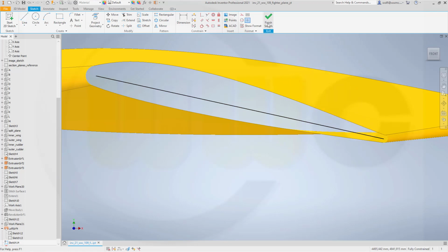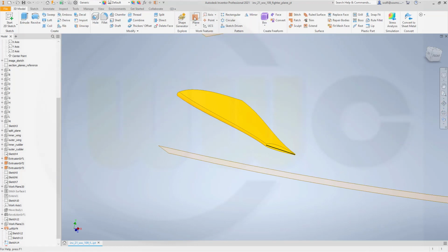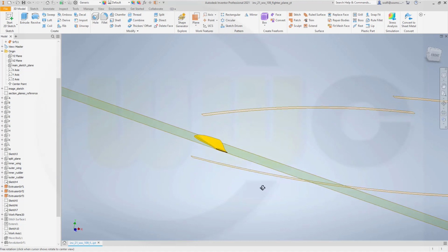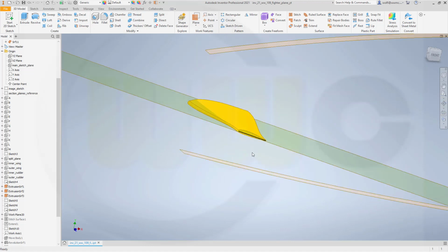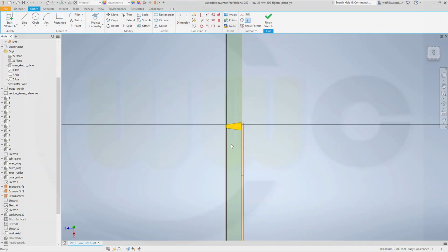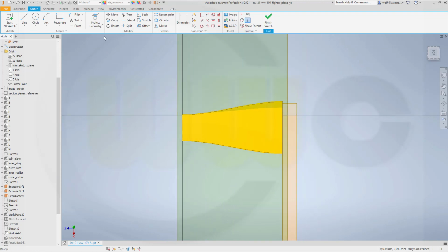And this works. So now I need a plane with an angle, so select that line and select the main sketch plane as reference and confirm. That gives me a new plane which is necessary for my wingtip here. Now for a new sketch on that just created plane. And I want to intersect, project cut edges with this surface.